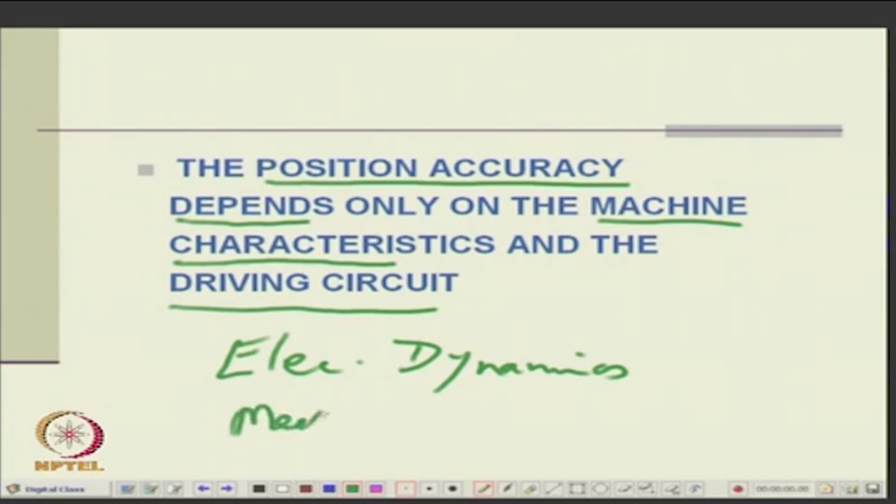There is also a mechanical dynamics. What is the mechanical dynamics? It develops a torque, and that causes motion opposed by friction and opposed by inertia. So, that is the mechanical dynamics. The movement decides the current response, and it will decide the theta response.